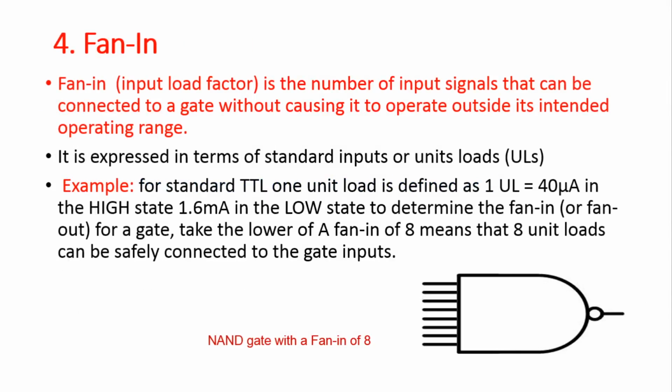Now the fourth one is fan in. Fan in, input load factor, is the number of input signals that can be connected to a gate without causing it to operate outside its intended operating range. It is expressed in terms of standard inputs or unit load, UL.